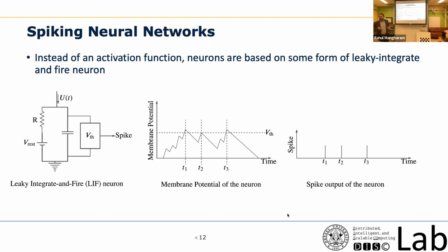A capacitor cannot hold charge for a long time. A capacitor is fundamentally two plates with charge inside it, and if you don't do anything, it will lose charge through the leak paths surrounding it. All the leak paths will be formed and the charge will start losing. VTH is not a component, it is just a threshold voltage I'm representing.